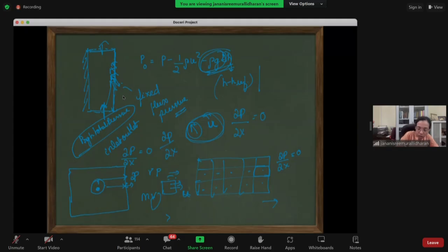Internally, it's not a fixed condition. What it will do is, this u prime, it will substitute in this expression, it will say calculate the flux, and is all the mass flux equal to the pressure difference, it will solve, like the continuity equation will accordingly get fixed. Am I making myself clear? It's not like a single expression. It's the continuity equation that you will have to solve.